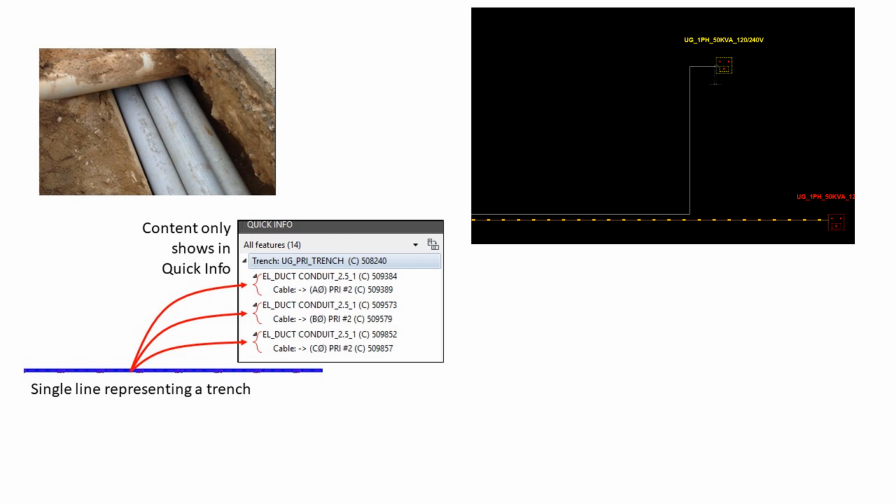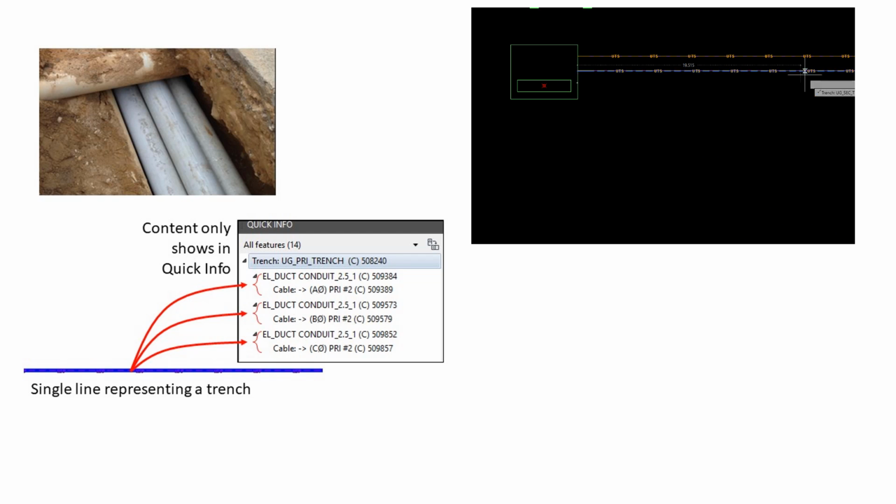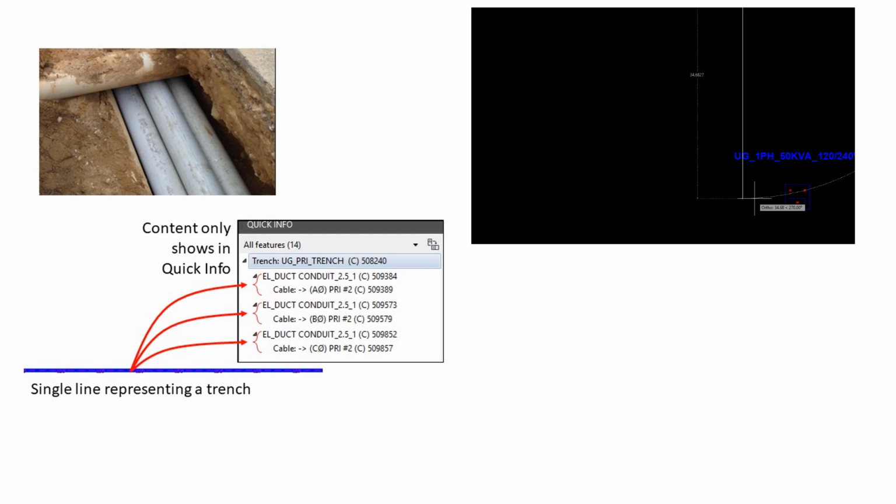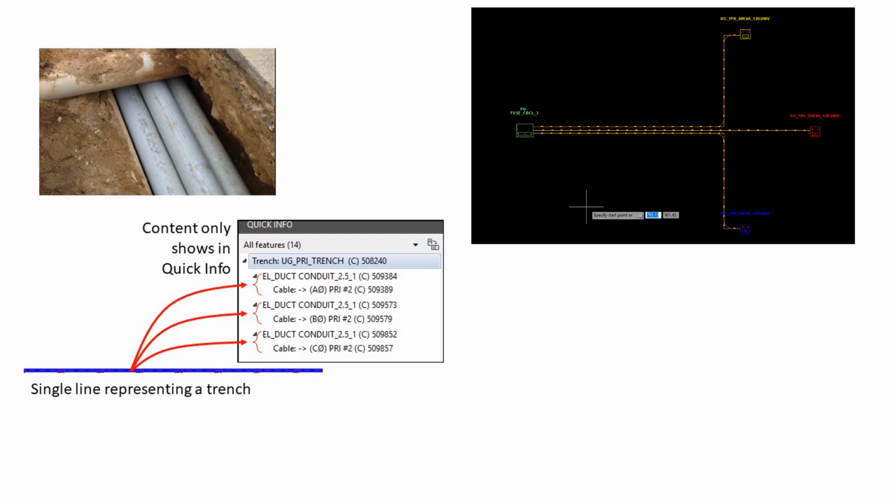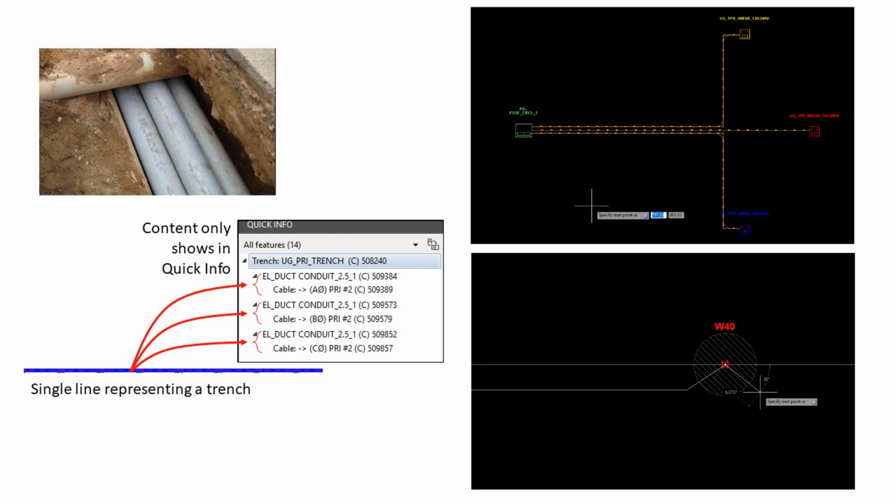Length measurements may not be accurate. Things may not connect properly. With underground lines, conduit bends may be ordered when you didn't want them ordered. And with overhead lines, poles may be inserted where they don't actually exist.